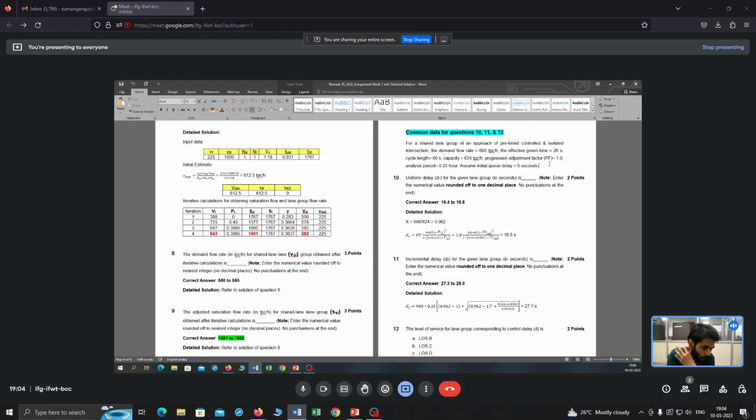So you are coming from the upstream signal, but you are seeing the downstream signal. There is always some queue, so your signal is never free of queue in those situations, right? Because your demand is always consistently greater than the capacity. So there is less chance that stability will be there, because it is instability. So there will be instability, right? As long as your demand is always greater than your capacity, right?